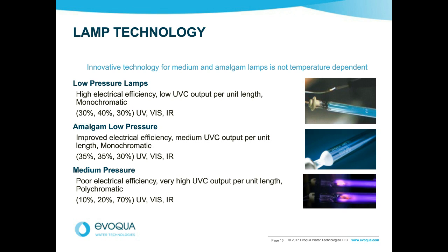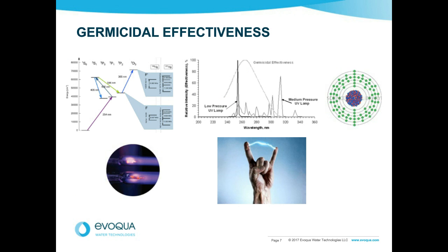If we go back to study the germicidal efficiency, if we go back to an earlier slide in the presentation, I'm just going to find it now. We can see, if we go back to this slide, in the middle, the low pressure UV lamp is one single output at 254. The medium pressure output is much greater. We've exaggerated the scale. Had we drawn these to scale, the low pressure output would be a small dot. The germicidal effectiveness has a peak at 265 nanometers. What we want is UV around the 265 nanometer mark. That's where it does the most damage to the DNA. So yes, each lamp has its own spectral characteristics. We build lamps from synthetic quartz for the deep UV for TOC removal, and we build lamps from regular quartz for regular disinfection and for use in pools and recreational water.